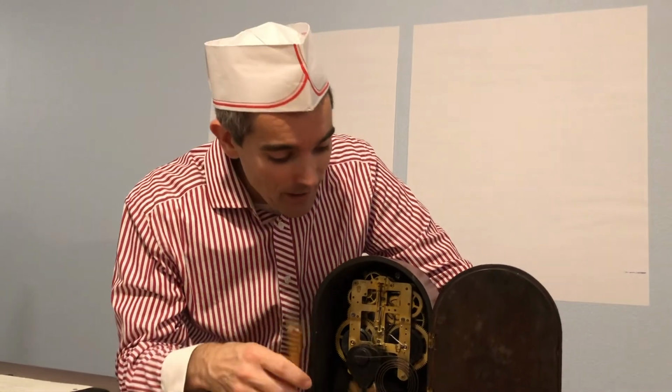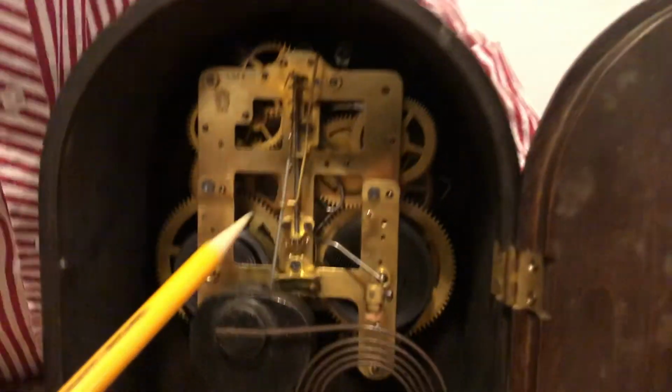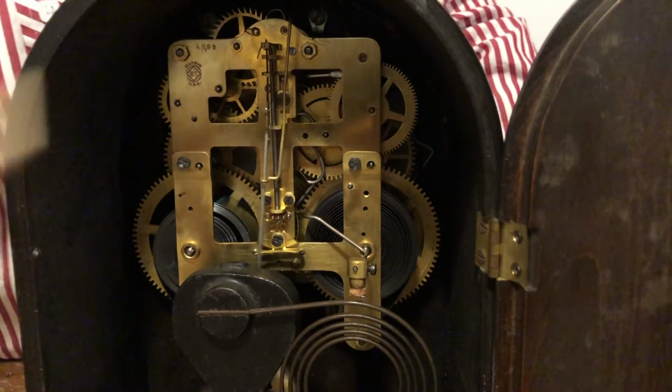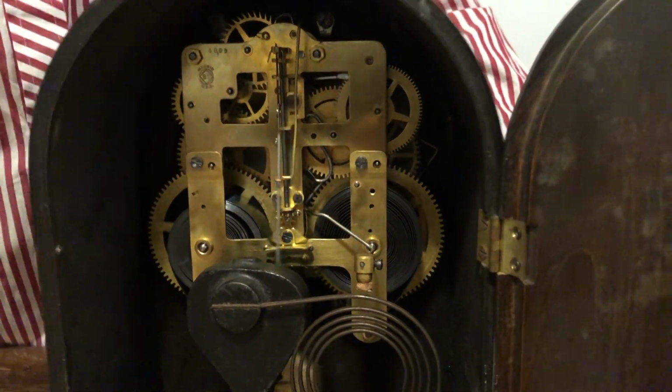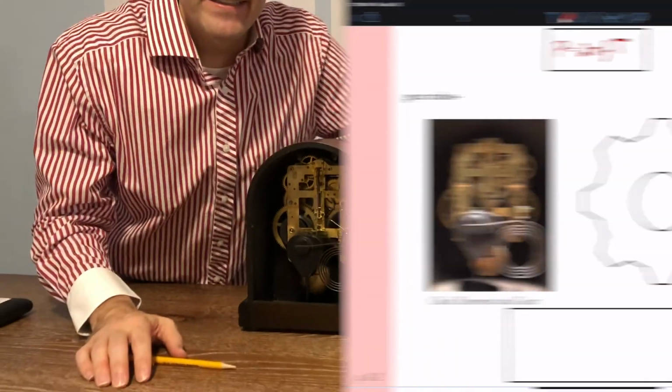Now that we know how power and torque are related, let's examine further gear ratios and see how we can use gears of different sizes to help scale the torque up and down from one gear shaft to the next. So engineers use this a lot. Whether you're using this in your car, perhaps in your transmission, which is maybe where most of us encounter this day to day, or if we come back to our clock, we're using a bunch of different gear sizes to help power up and power down those torques from one gear shaft to the next.